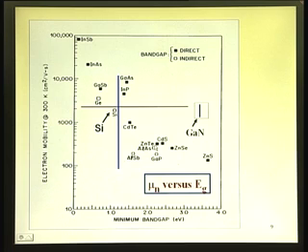You don't like to take a look at those materials whose mobility is much smaller than that of silicon, though the band gap is very good. And I am just going one by one so that you get a complete feel for the thing. Zinc selenide again, 2.8 electron volts band gap. Mobility very poor, something like 300.